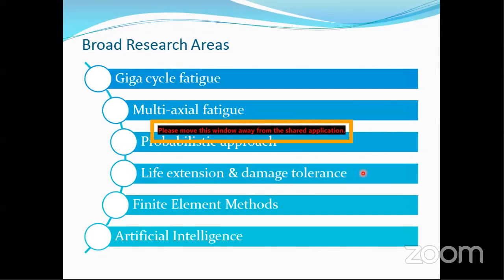Here it is done by using interference fit, or using stiffeners, or even adhesive plates. Different studies are mostly at the laboratory level, and they scale these results to the actual component by using certain factors based on some assumptions. Most of these studies give only an approximate value of fatigue life or crack propagation. There will not be any exact value.